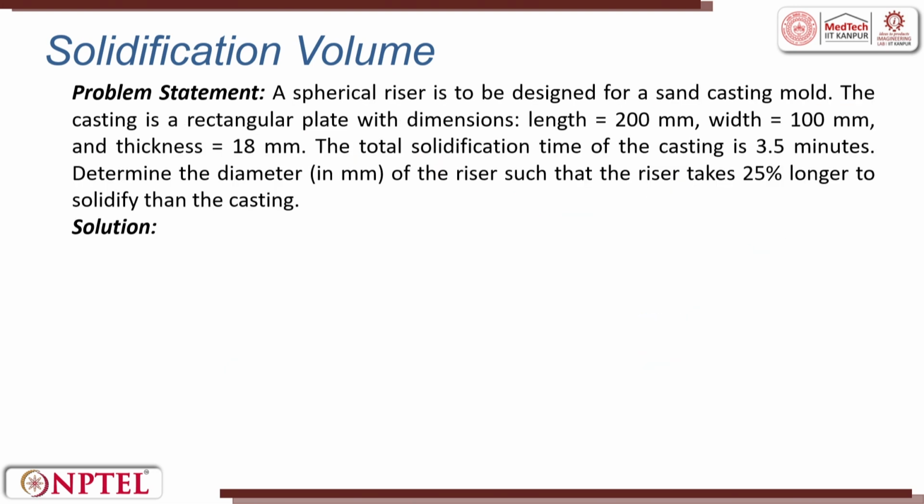Next, I will talk about the riser, sprue and gate design. Using the solidification time and the volume to area ratios, let us try to see another problem statement where we will design a riser. A spherical riser is to be designed for a sand casting mold. The casting is a rectangular plate with dimensions length 200, width 100, thickness 18 millimeter. Total solidification time of the casting is 3.5 minutes. Determine the diameter in millimeter for the riser such that the riser takes 25% longer to solidify than the casting.